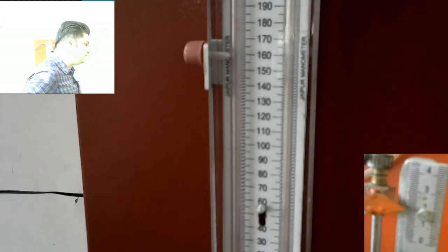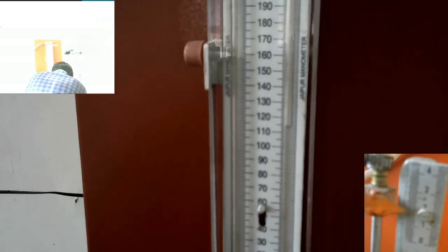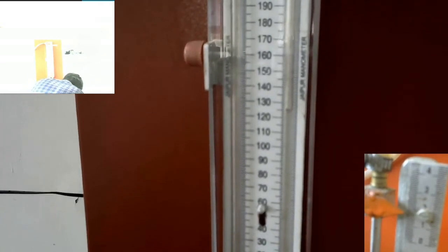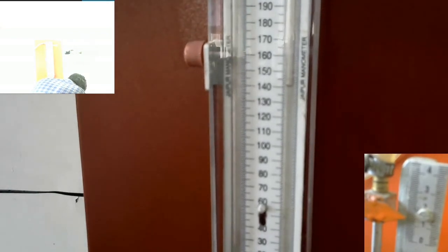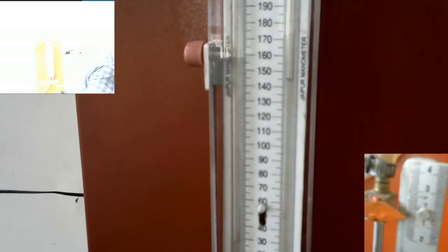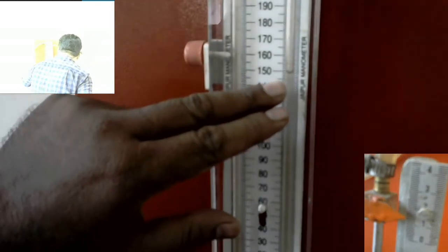Well, we repeat the same procedure for another 3 readings, where I go down again to 1.5, as 2 is already done. So we go to 1.5. So we're down to 1.5. You can see that on your computer screen. And that will lead to a change in the manometer reading also. So the lower reading is now around 34, 35. So I'm maybe down at 34 at 1.5. And the upper one is at around 150.